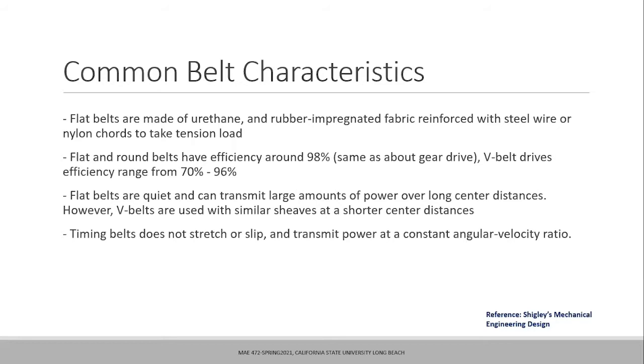In addition to that, the advantage of flat or any type of belt drives is that you can accommodate longer center distances between the two shafts, the input and output shaft. So if you have longer center distances and you do not want to have gears engaged between the input and output shaft, you can transmit the power using belt drives. So belt drives allow you to have the option of greater center distances between input and output shaft. And at the same time, the efficiency is almost similar to gear drives.